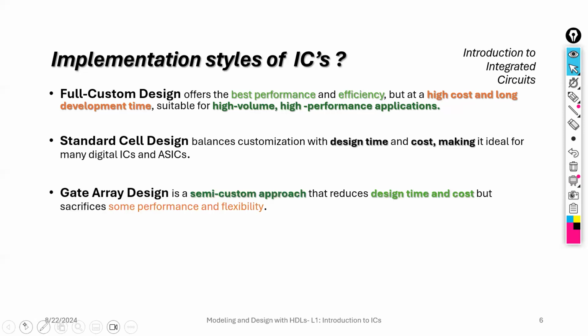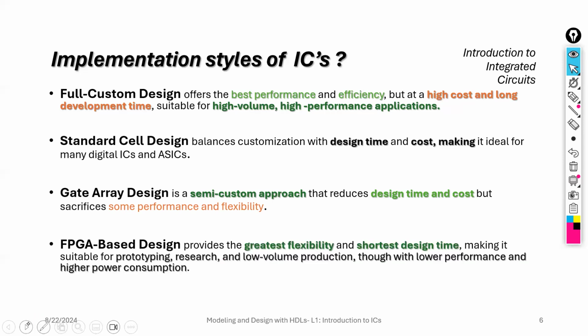Whereas the gate array structure is a semi-custom approach. Design time and cost are also very low here, but we need to sacrifice performance and flexibility. Next, FPGA based design provides the greatest flexibility and the shortest design time.